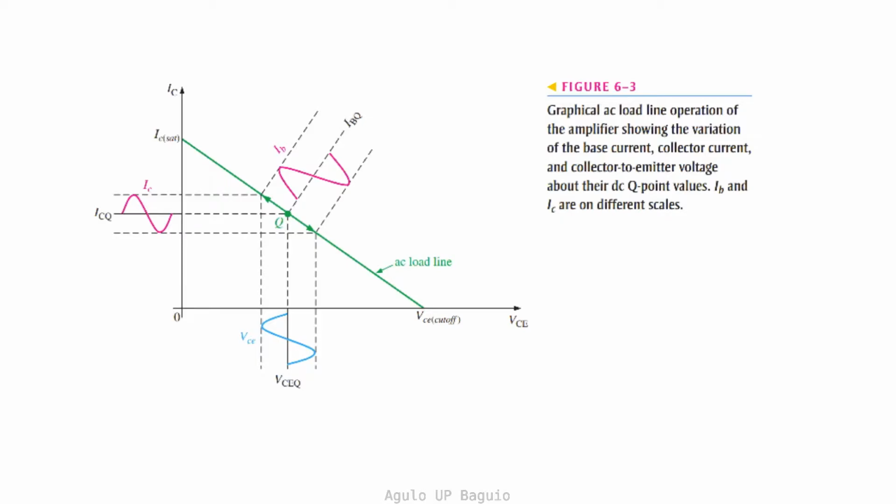If we take a look at the transistor load line, we can appreciate more how the phase inversion works. The Q point is indicated along the load line. The input signal is indicated as the red sinusoidal curve, while the output signal is the blue sinusoidal curve. At the Q point, the base current is amplified as the collector current.